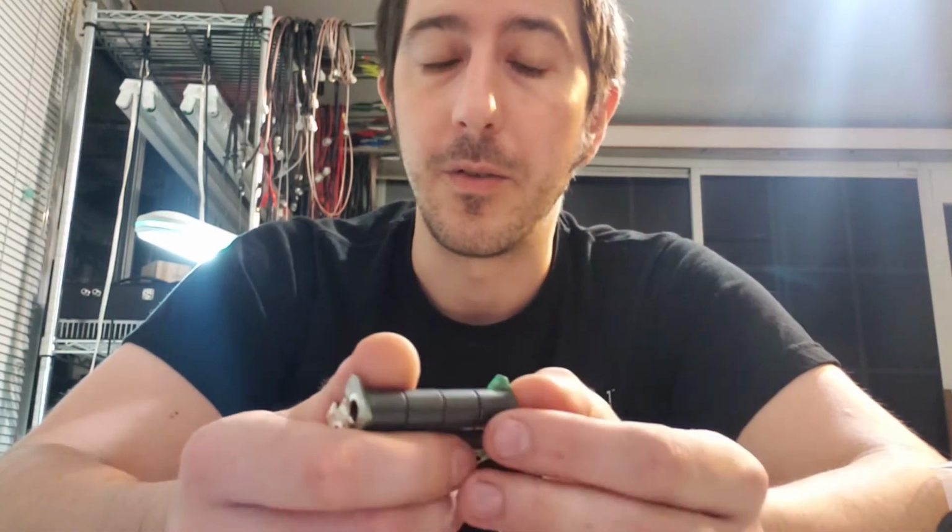And you do that with capacitors. You can do it with inductors as well. You can do it with a handful of different types of components. But capacitors are by far the most common, especially in the HF frequency range. The lower you go in the HF frequency range, actually, the less you have to compensate these things. As frequency goes down, things start to work a little more perfectly. Magnetizing inductance and leakage inductance don't have such a big effect.